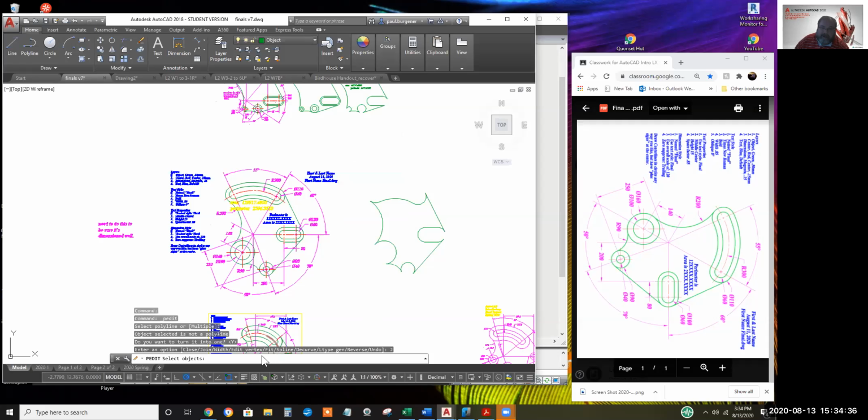Now it says select objects you want to weld. It's tempting to click it, get all the way around all 13 remaining pieces, but being incredibly lazy, I'm just going to window them all with a crossing window. And there's no harm done if you over select. Only those objects that are joinable will be worked on. It will be welded to the original.